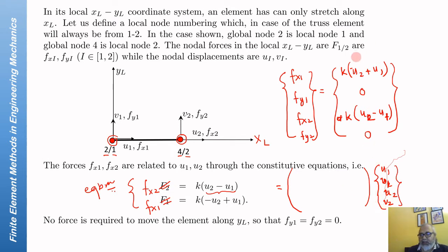And then I'll have to write these equations. u1 is multiplied by k, Fy1 is 0, so 0 here, minus k here for the u2, then 0 again. For v1, this row should give me 0 because Fy1 is 0, so this is all zeros.